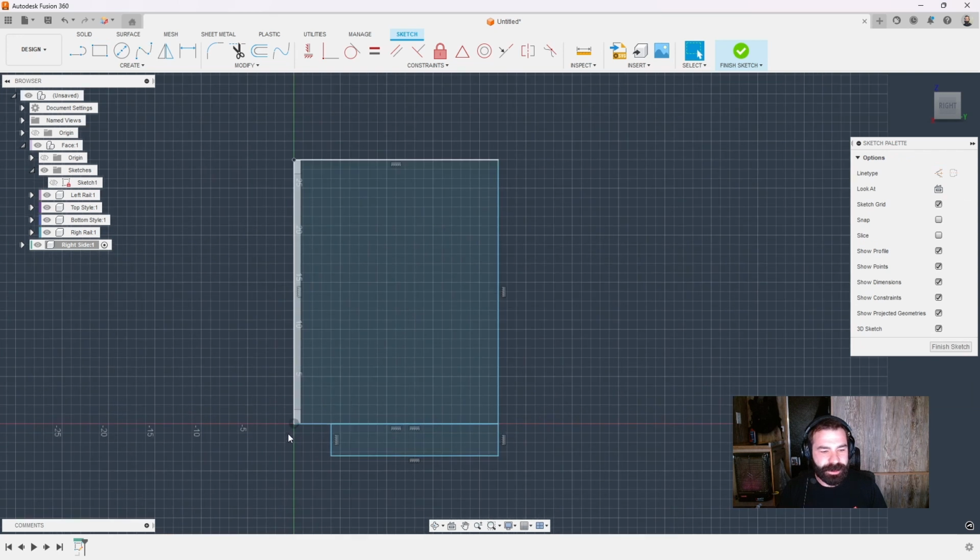So a few things that we want to do is we want this actual shape to be automatically controlled based on that faceplate. So again, as I'm using a coincidence to set the front, I'm going to normal dimension with a hotkey, the depth, and the recess portion for that kick plate. And again, lastly, I need a total depth of my cabinet, which is why I'm pulling my dimension from the front face. So we have 22 inches. Let's just round that down and get that set.